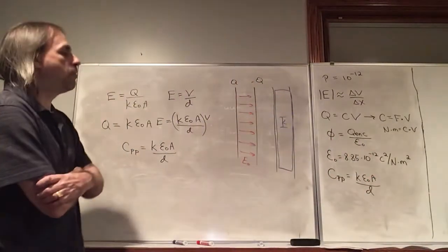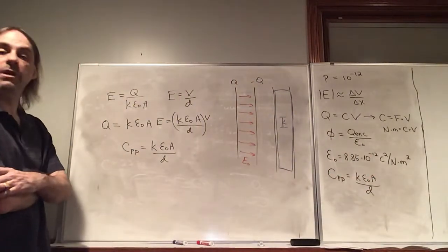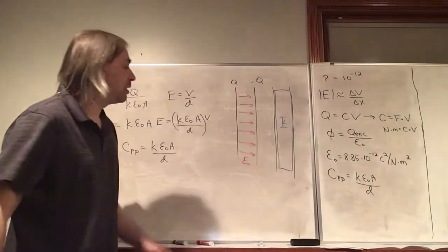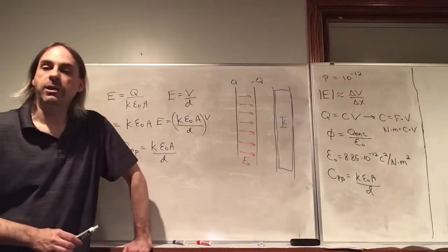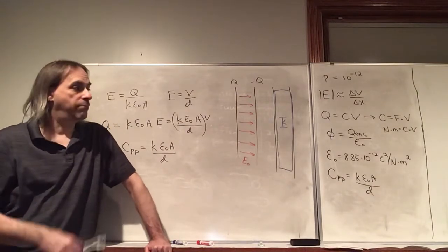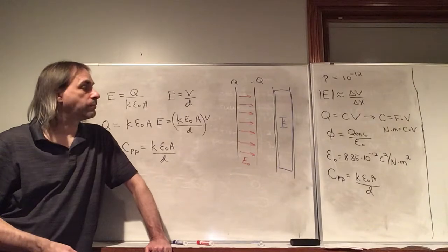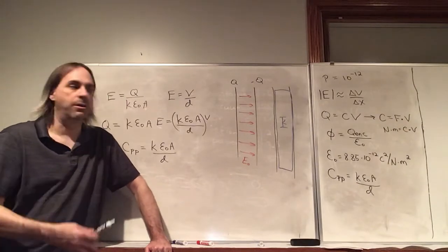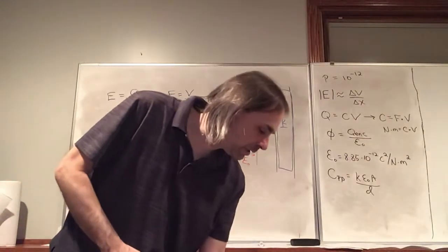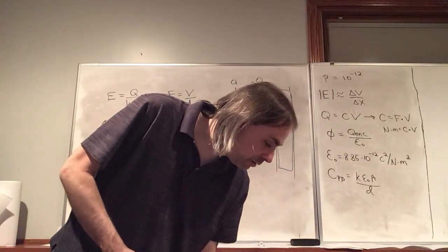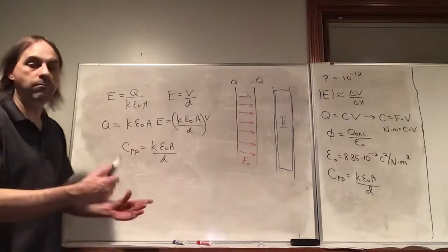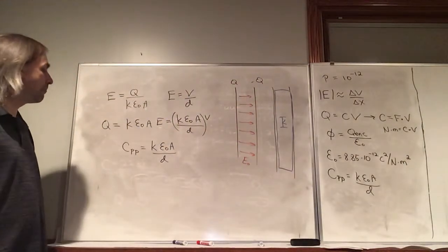So I'm actually going to put the K over here because this is true in general. So yeah, for the parallel plate capacitor more generally, if you have a dielectric material, basically you get the same result as before, but you multiply by the dielectric constant. And again, we saw that can be a significant factor. Some materials you could easily use in electronics, not like water, but the biggest solid here was rubber, which was 6.7. That was fairly significant.